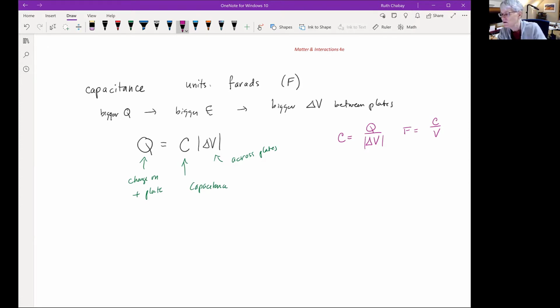Well, the transient current of the circuit with only the charged capacitor, is it just the result of built-up surface charges redistributing? There are two things contributing to that current, the field in the wires and in the light bulb that drives that current. One is absolutely surface charge, and the other is the field of the capacitor itself.